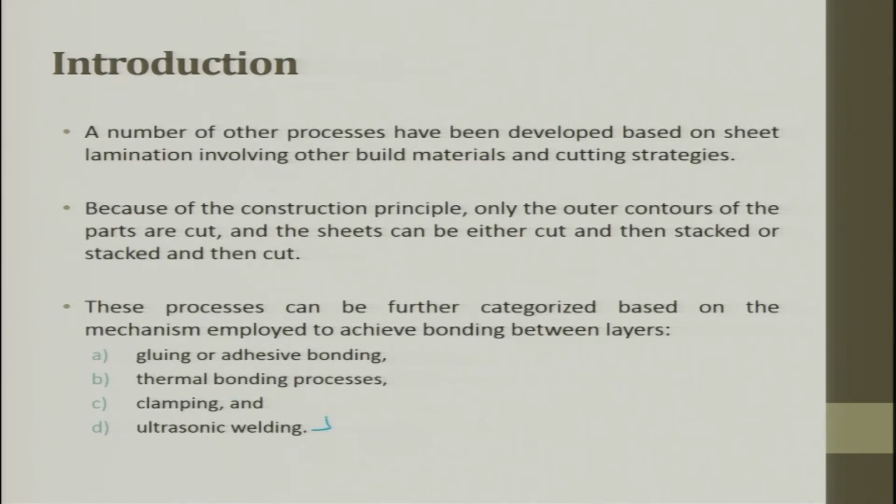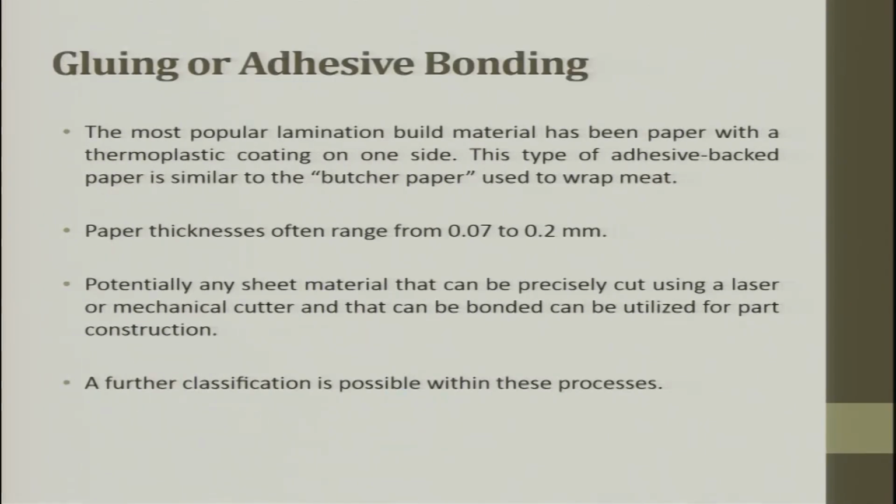Ultrasonic welding, as such, is used for polymer processes. If you want to join polymer, we use the ultrasonic welding process. You can also use metals to do it. Basically, when you do metals, the oxide layer is removed and the nascent layer comes in contact, and it glues. So, between layer to layer, you can use ultrasonic welding and start gluing it.